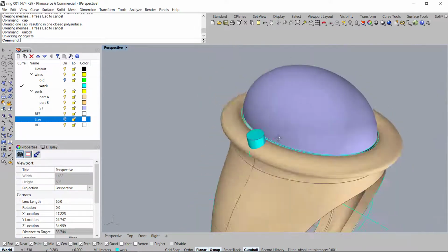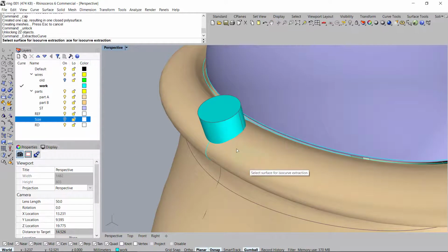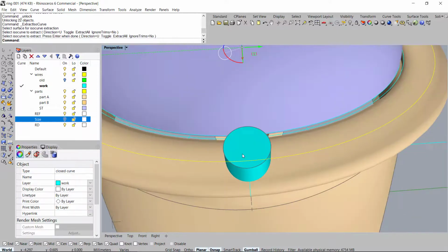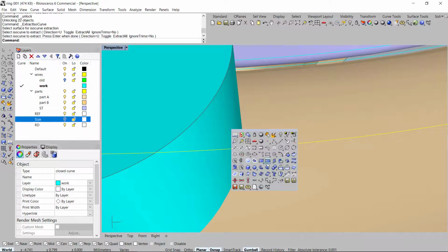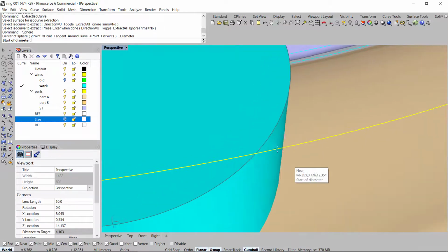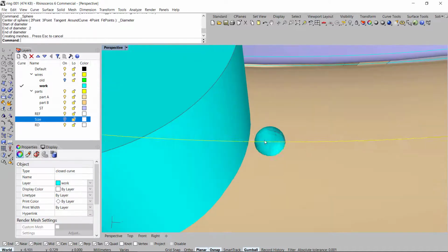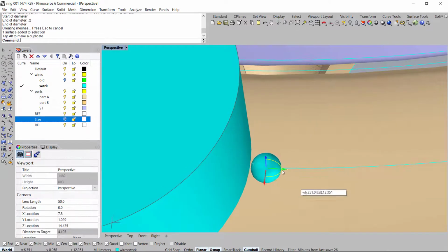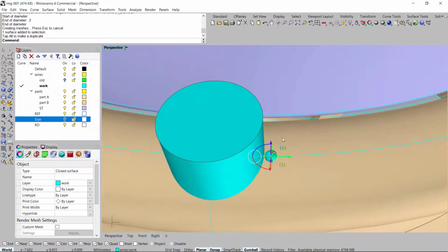One last thing is just to array this around. I do want to create a guide here because you want to make sure when you space these cutters that there is a distance between the stone. The distance I like to use is, let me first draw it. I like to make sure that the distance between both stones is 0.2, so I'm going to draw a 2-point circle, type in 0.2 as a diameter, and when I array it I want to make sure, let me just manually move it, that the cutters are 0.2 or close to 0.2 in spacing.